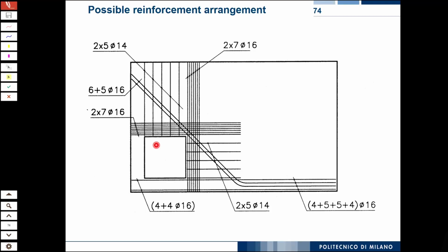So a good thing would also be to try to see, okay, when I design my reinforcement, how many leftovers? If I have a 7-meter bar here, can I have somewhere else a 5-meter bar that I use, cutting the 12-meter long one?